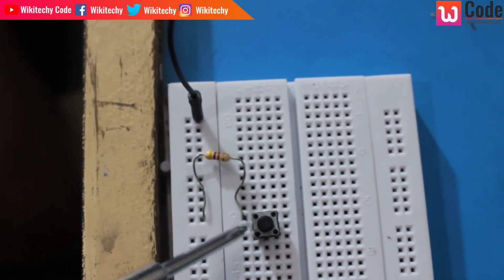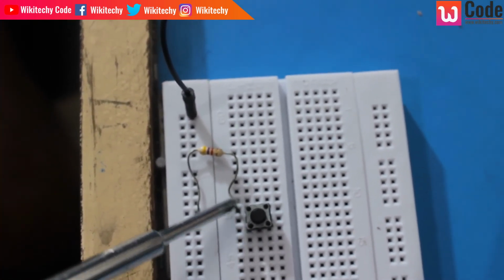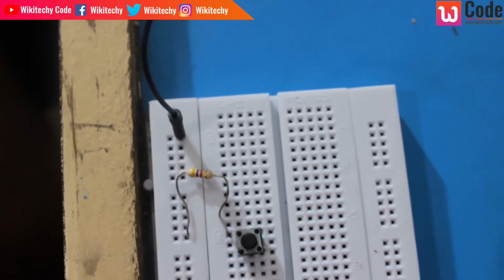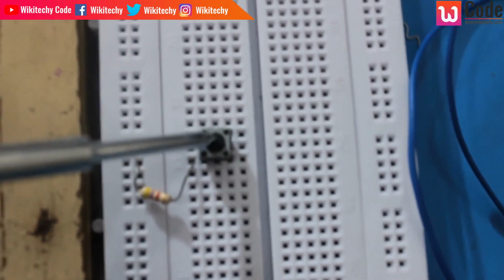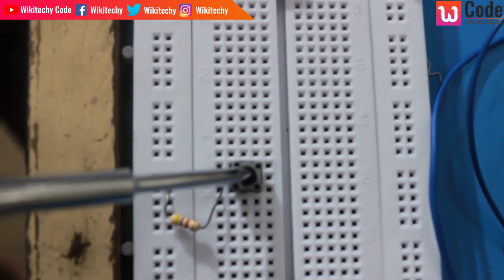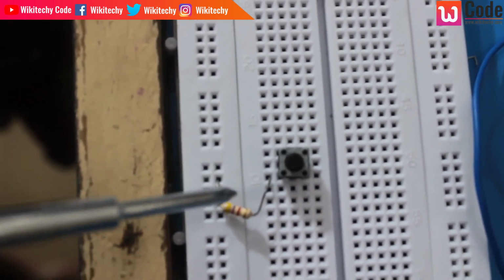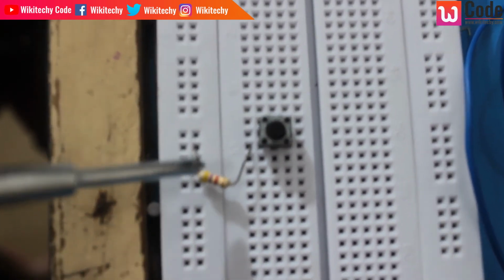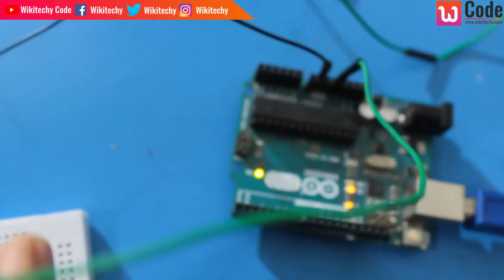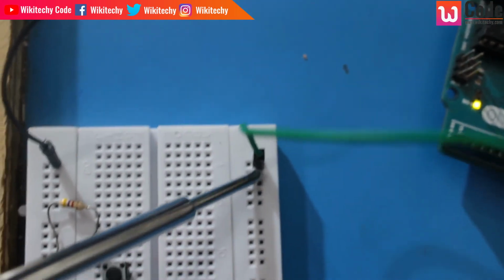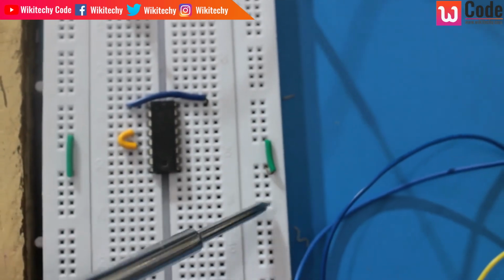This resistor is to remove the unwanted pending current or stray current, and it's grounded from the switch which is available. The same thing here, I got the switch. If there is any pending or unwanted current or power supply, that will be taken to the ground via the resistor. This is of 4.7 kilo ohm. Now I got my 5 volt, which I'm going to connect to this particular pin, so that on the whole it got 5 volts supply carrying on in this entire breadboard.